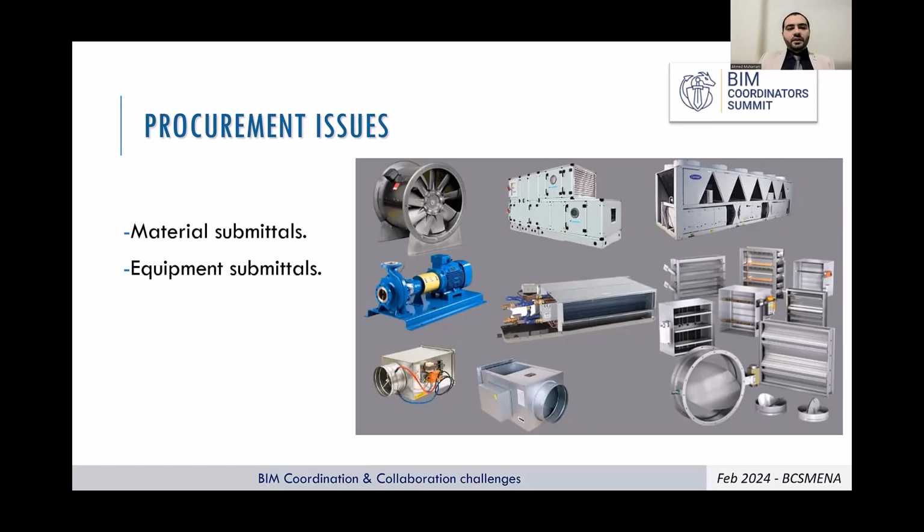In this situation, you have to make the coordination with proper clearances, because if you don't have clearance from the machine to the left, you will not have space to change the pipe from right to left. It is very important to take into consideration the risks you have in the project, and they should be included in the BIM documents at the start of the project. It's the risk register.